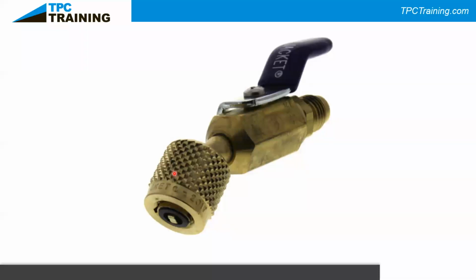Problem is, if you don't have those quick connect gauges on there, then you're going to release that 5-foot, 6-foot pressure in your hose into the atmosphere, and you're going to take more pressure out of the system. So the idea is when you're hooking up your gauges, you want to try to not have as much refrigerant coming out of your hoses because the system charge needs to be dialed in where we want it to be exact.